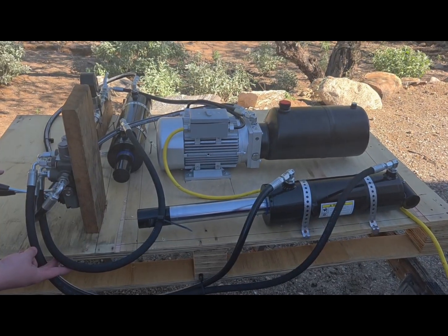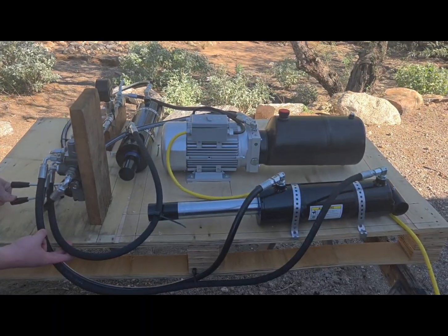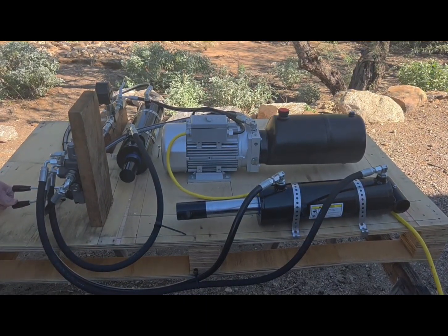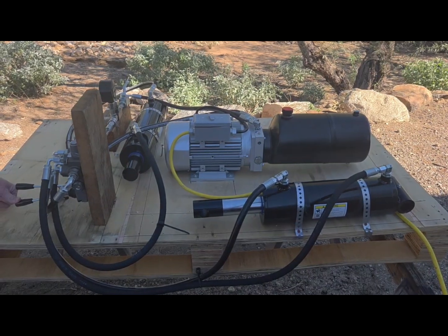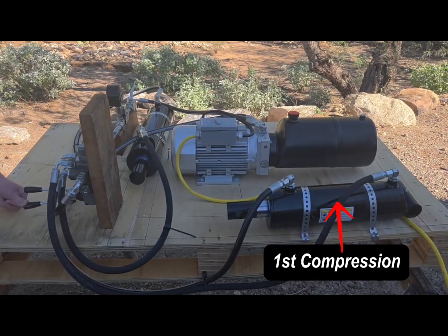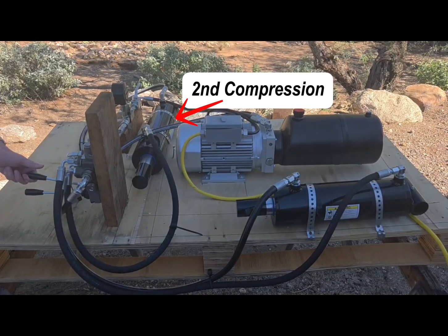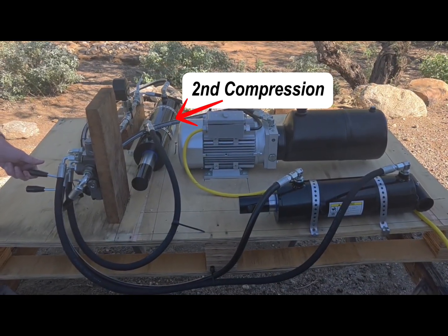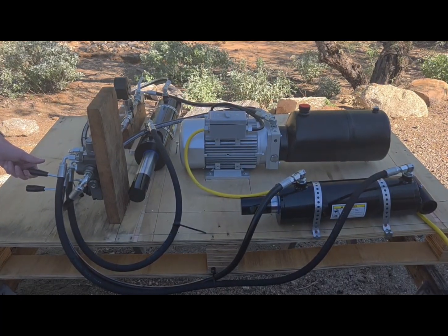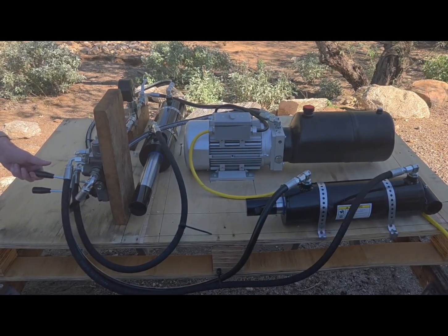In this part of the video, we're highlighting the key concepts that allow our system to actually achieve high-density bales. The most important feature is our dual-cylinder compression system. What you're seeing here is the hydraulic cylinders extending and retracting, which drives the entire compression process. We designed this as a two-stage system. The first stage applies an initial compression at a lower pressure to compact the loose material and remove large air gaps. Then the second stage applies a much higher pressure to further densify the material and form a solid, uniform bale. This staged approach is important because trying to fully compress loose scrap in a single step isn't very effective. It leads to uneven packing and limits the final density of the bale.